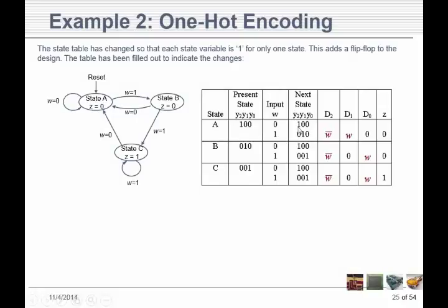Well, that looks like not W. So that's what I have to connect to the input of this D flip-flop. Here, on this second one, 0 on 1, and this is 0 on 1, so D1 is exactly what the input W is. And on this third one, it's real nice for us because it's 0 no matter what, so we just put a 0 at the input there.